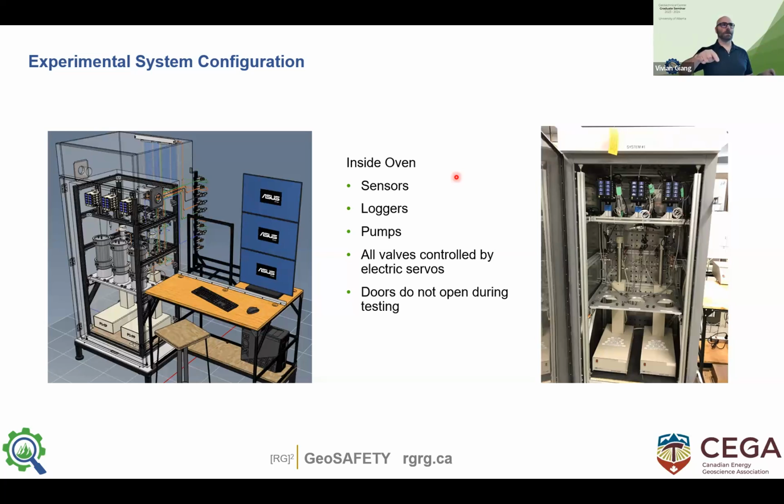If you're looking to measure really small values, all of that comes into play. So if you have temperature and resistance and power, you can actually see it fluctuate up and down as the temperature in the laboratory changes. So it may not impact your work, but it may be something that you might want to pay attention to, or probably pay attention to. So you can log the voltage coming out of your power supply and log the temperature in your room and see how they correlate.